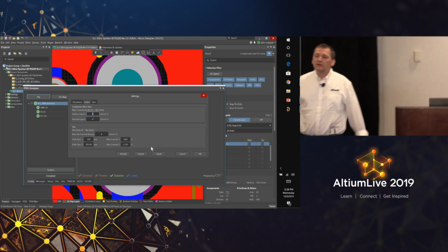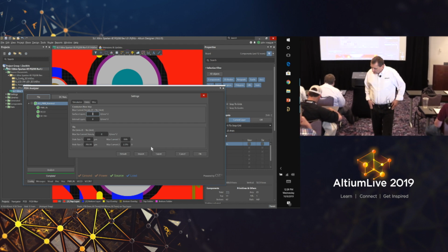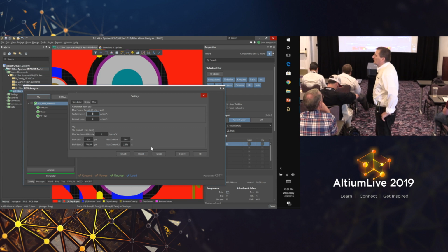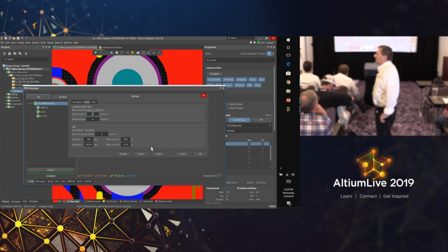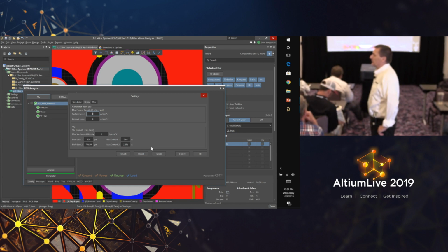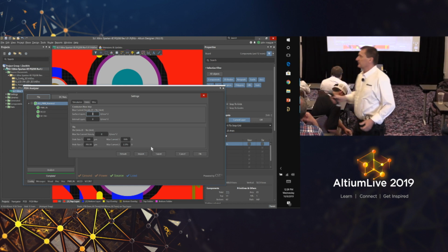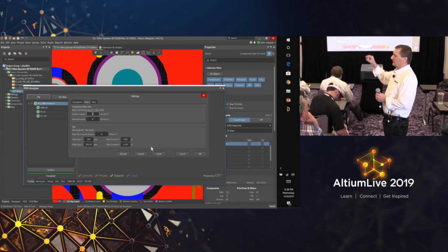And so will the program automatically pull the smallest and largest via size from the design, or do we have to go back and look at that? You'd have to specify that. Okay. And that's easy enough in one of the browsers to list order by hole size. At the PCB panel, you can select via and then have them lined up to see your max and min.